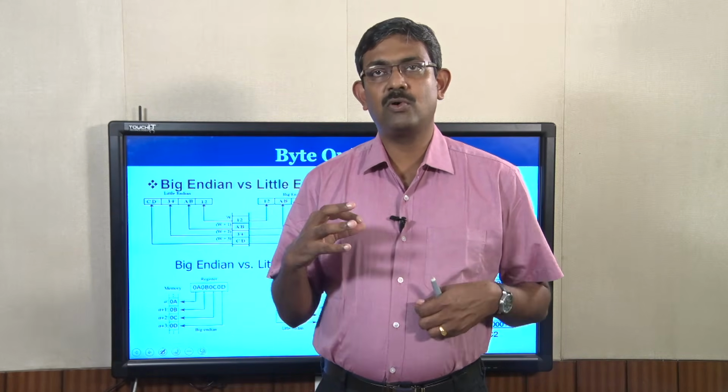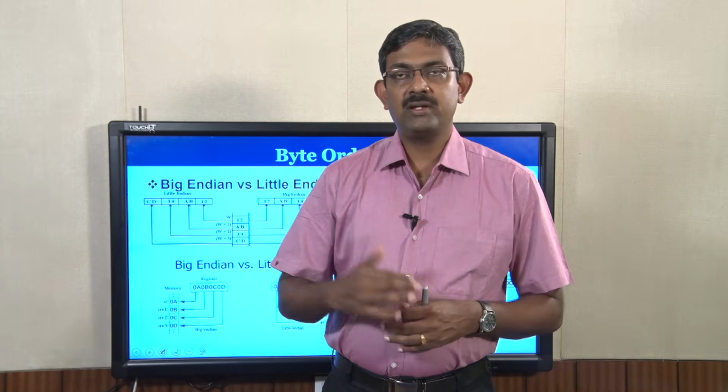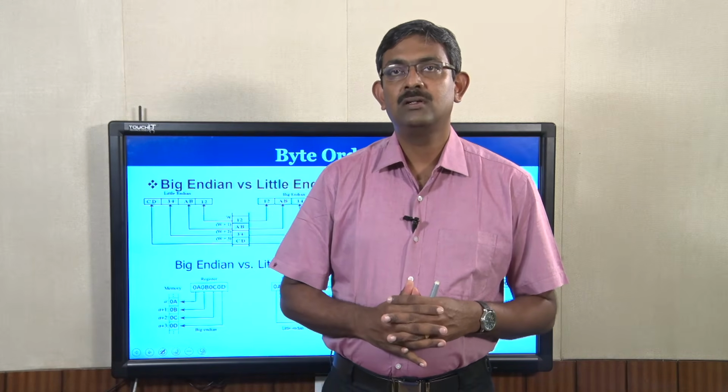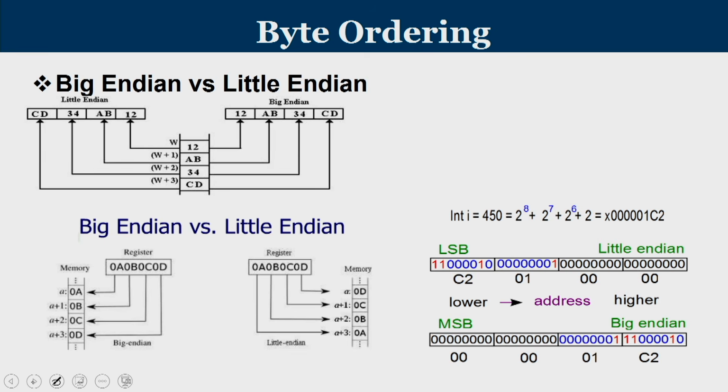When the processor is going to read and write larger words, when it comes to storage inside memory, we have to understand in what order they get stored. So, there exists a format in which multi-byte words are stored inside memory. They are little endian format as well as big endian format. We will now look into what the difference between these 2 storages is.